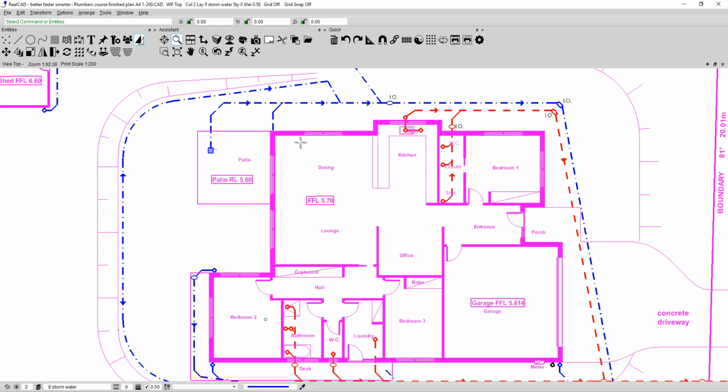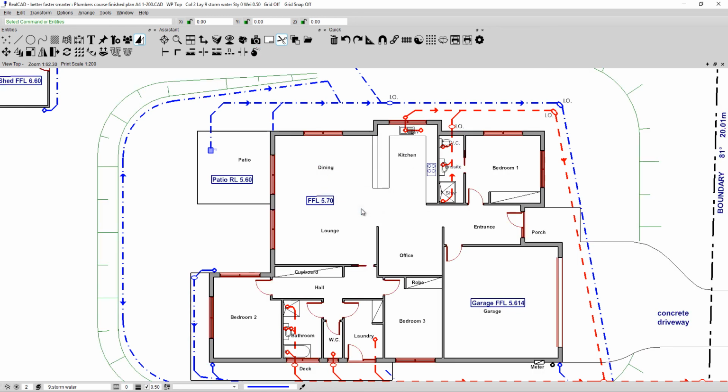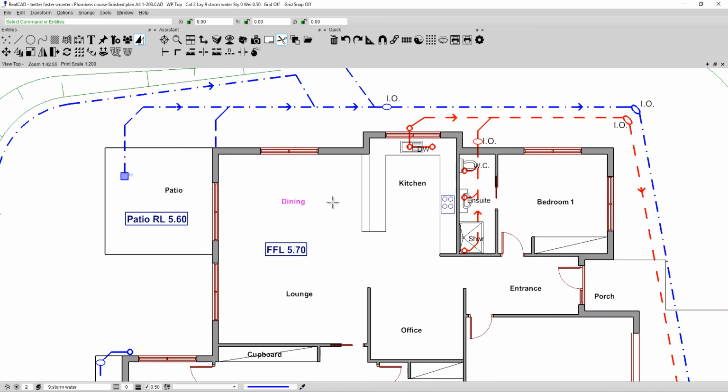So to explode, you would come up to the scissors, the bomb, you delete the existing entity, that would always be ticked, and then you'd select OK. Nothing appears to have happened except that if I now touch the text, it's an independent object. And I could use it to copy around if I liked that type of text better than I liked this type of text that I've got going up here.